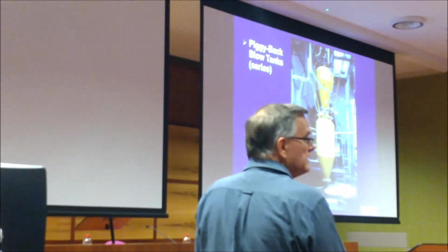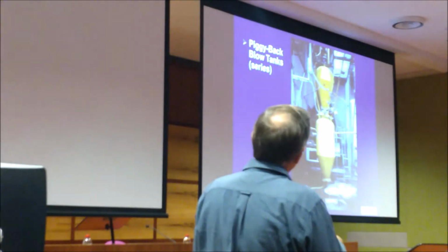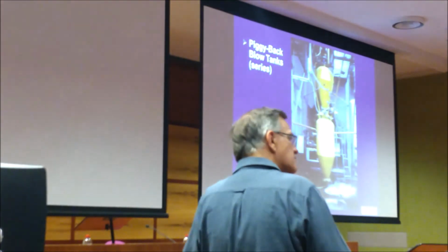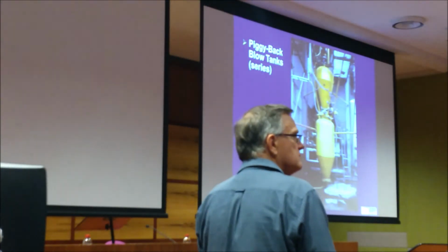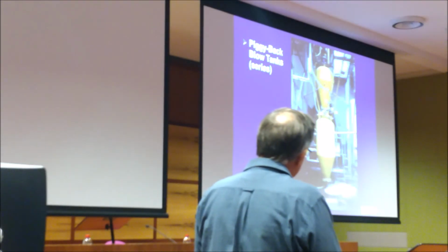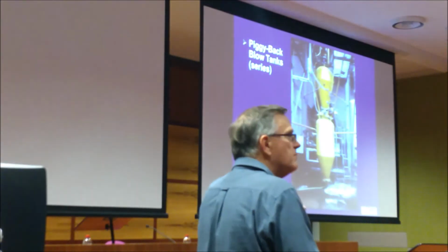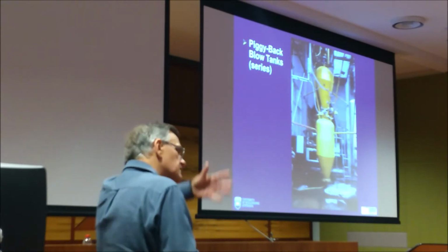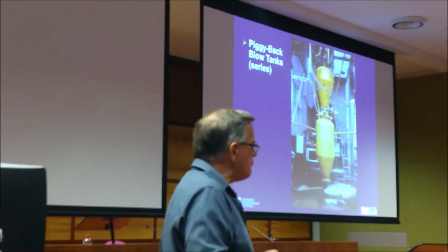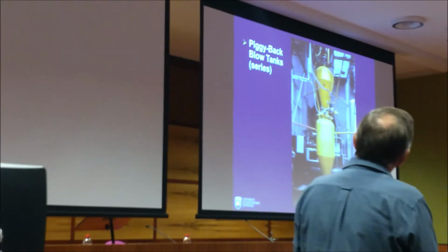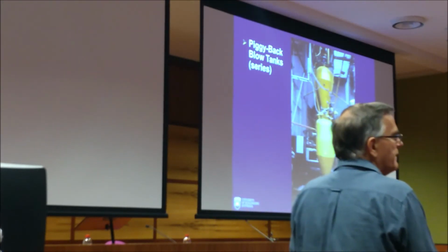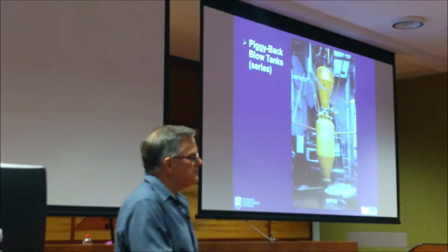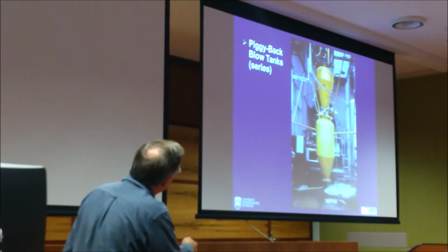And then we vent that to your silo filter. And then that goes back to atmospheric condition. And we can refill it, make it ready for the next cycle. When that material level drops again, we make sure that one's ready to drop. Okay, and then we just balance the pressures again. We don't want any sort of residual pressure across that valve. Otherwise, you might blow a little bit of air that way or blow it that way, and it upsets your feeding accuracy. Okay, so you can see the pipe here, this is your pressure balance line.